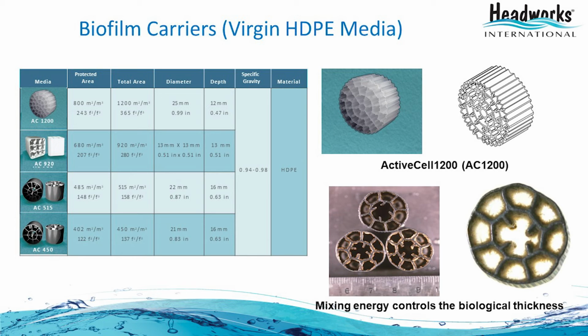That's the media that was invented by us in year 2000. Since then, we have made multiple versions of the media, each with a different type of surface area, different openings, and different fluid dynamics. Each one has some advantages, but they're all very similar in the sense that they're all made of HDPE, and they all freely move around in the tank, which makes it more efficient, because you will have efficient mass transfer of oxygen and BOD, ammonia, all the substrates into the media or biofilm.